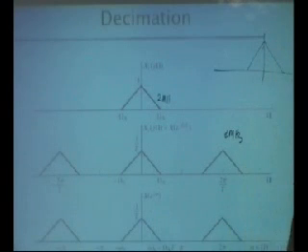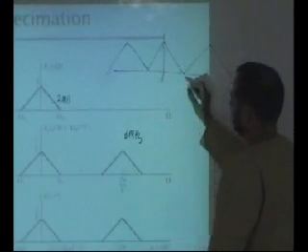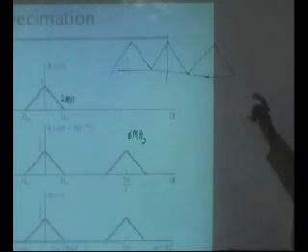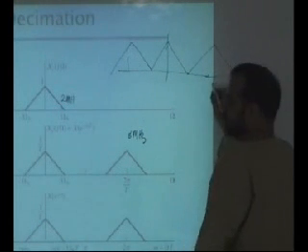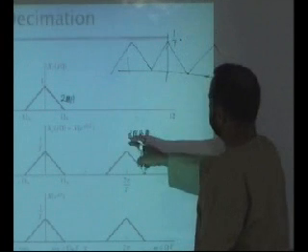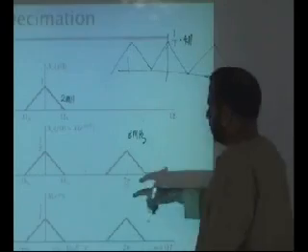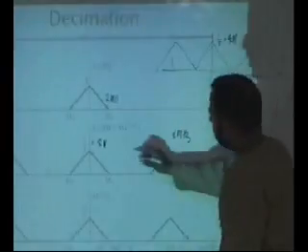The copies will be where? Right here, right? If you are sampling a 2 megahertz signal at 4 megahertz, this is what you will get, not this. Am I right? So this is what you get. So this is equivalent to the digital part. This is 1 over T, and 1 over T in this case is 4 mega. Oh, sorry, in the earlier case, 1 over T is 8 mega.